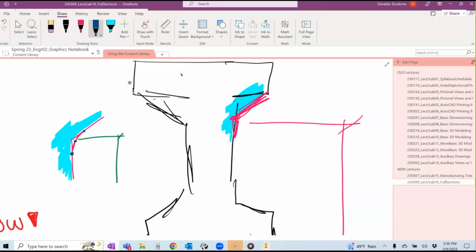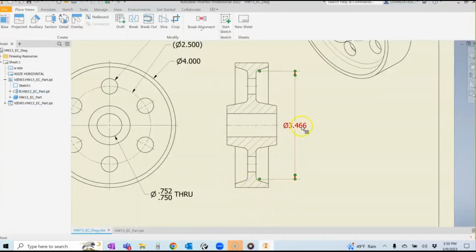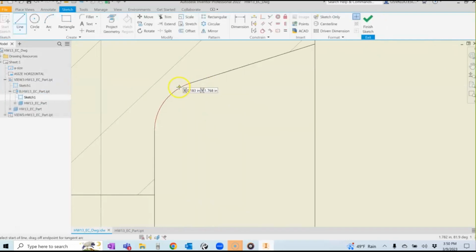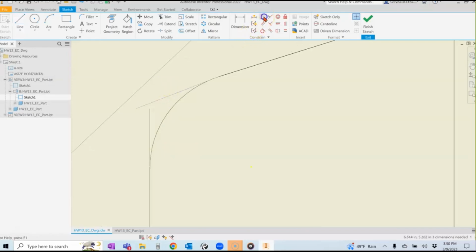We're going to do another trick. A bunch of tricks today. Okay. So I'm going to get rid of this guy, and I am going to go to the sketch mode. How do I go to the sketch mode? L for line, just like AutoCAD. I'm going to click on it, and as soon as I start drawing, I'm gonna click here and put it about there. Let's make another line. So I'm gonna make it straight. Okay. I'm gonna use this coincident constraint and put it right there. And then I'm going to align this guy to that guy, to make the little corner.